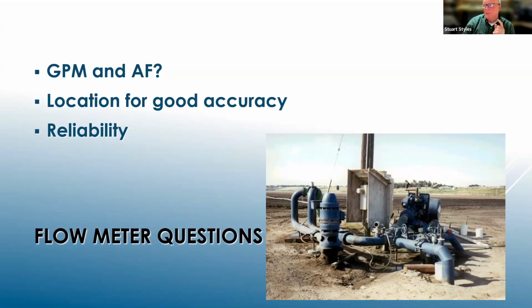The one thing I will mention is that you can't inject fertilizers upstream of a magnetic meter. That's something that I was using them for about 15 to 17 years before someone finally brought that up as a big red flag. And we did some testing on it. Sure enough, if you inject fertilizers upstream, it'll throw the mag meter into a tailspin of incorrect data. The reason is it can't handle changes in the electrical conductivity of the material that you're putting into it. That's the issue.